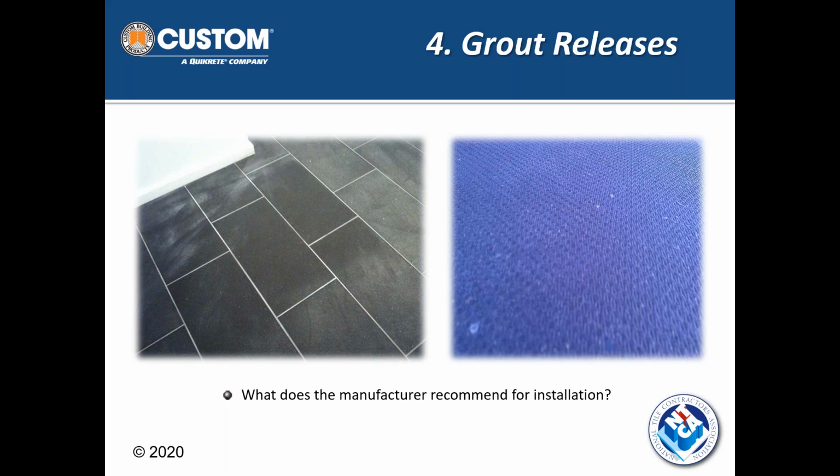So again, can we fix it? Sure. It would have been cheaper and easier to prevent it with a grout release. Again, not a sealer, but in this case, as I mentioned, a grout release. Because what's the picture on the right? That's the magnified texture of the picture on the left, about 160 or 180 times, something like that. It looks more like Velcro.